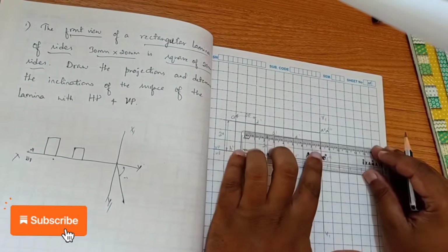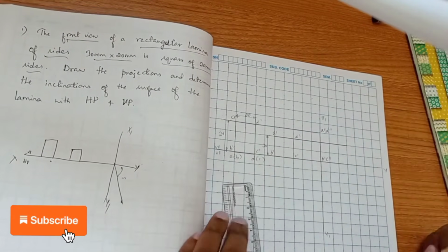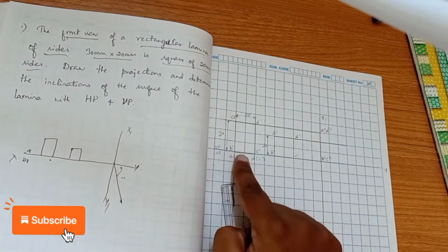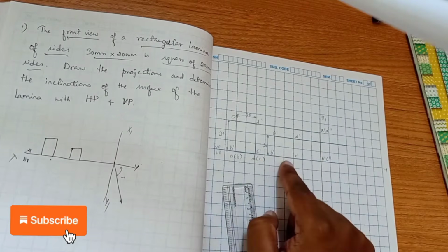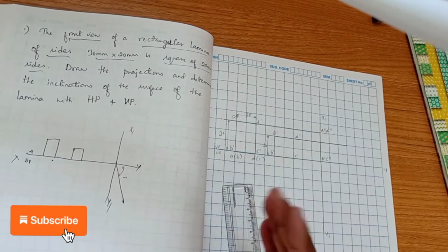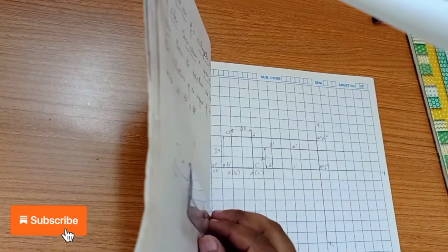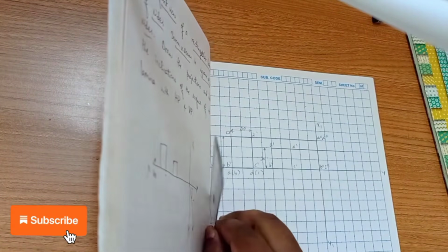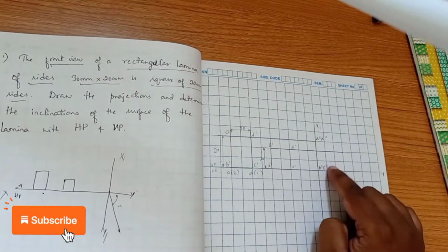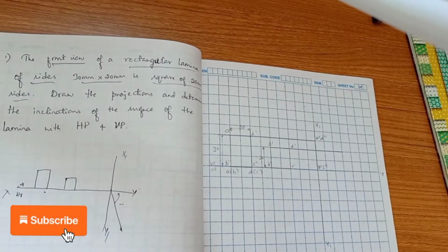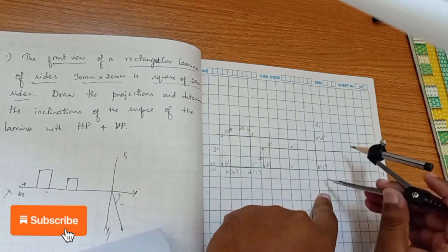Similarly for the second position, we have to get the side view by projecting here. So we know that this is the first lamina, and by inclining it by some angle we don't know, we're getting a square of 20 by 20, right? So this is what has been inclined like this. Say this is our first quadrant, this is our rectangular lamina and it has been inclined in such a way that we are getting a square of 20. Whatever the inclination is, we can show it in the side view. So say this is the side view of the first position, A double dash, D double dash, B dash. So this is the side view.